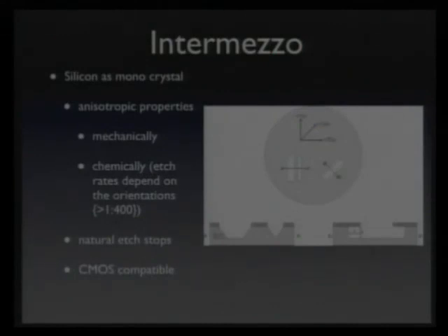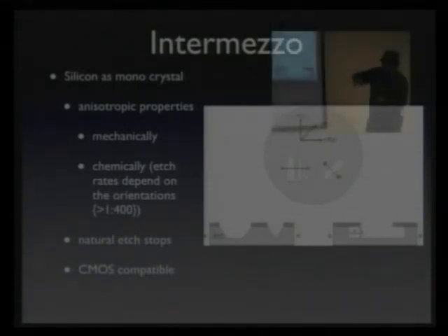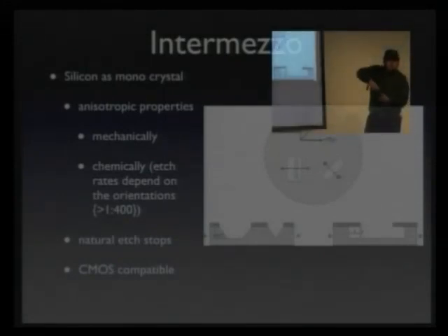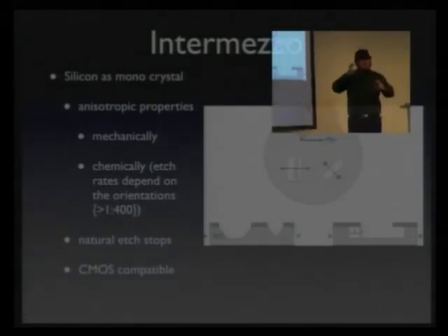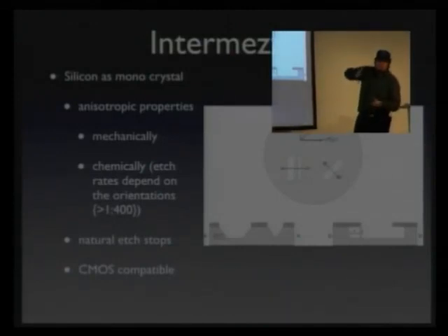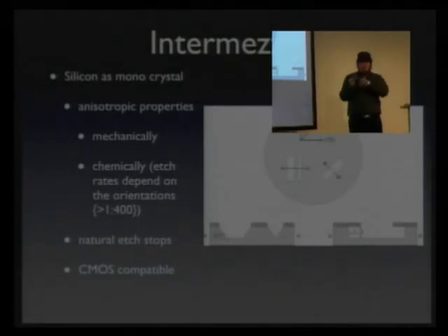When you buy a wafer, which looks like one of those, a normal silicon 3-inch wafer, they're actually made quite neatly. They have a big beaker of molten silicon, and then they have a seed crystal and turn this all the time and slowly pull it out so that you get a big silicon sausage, and then you slice the whole thing to get these small wafers, and then you polish it so that you have defined properties on it.